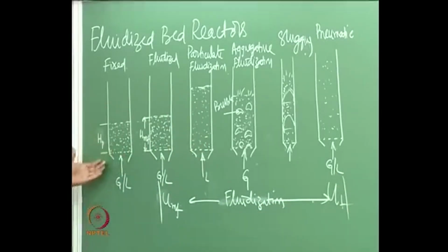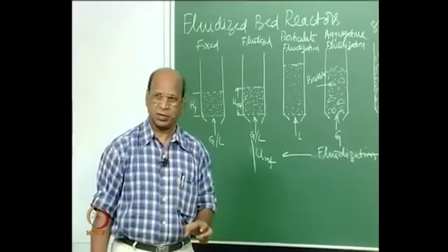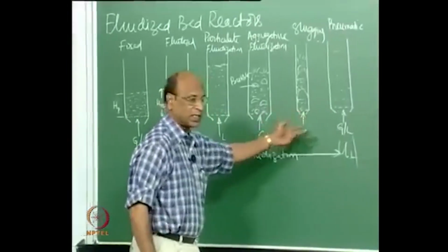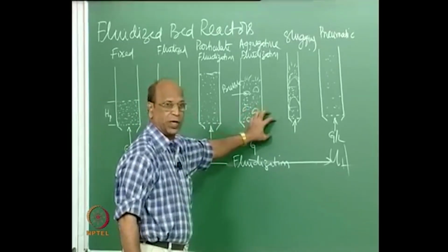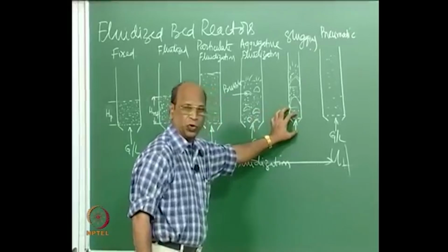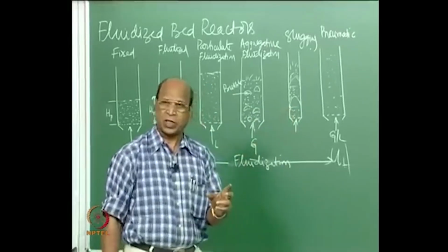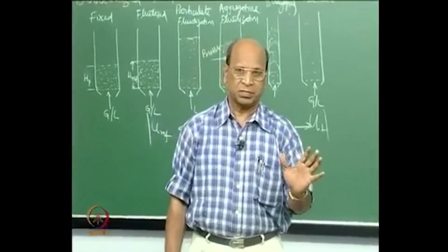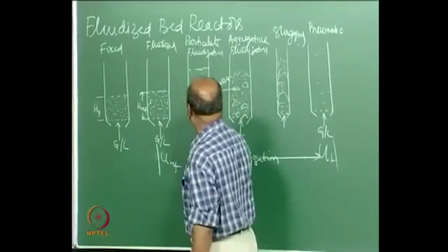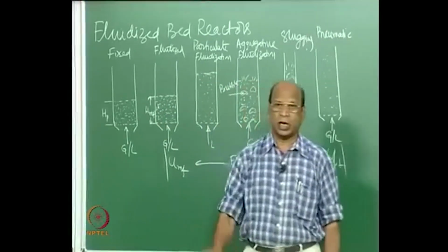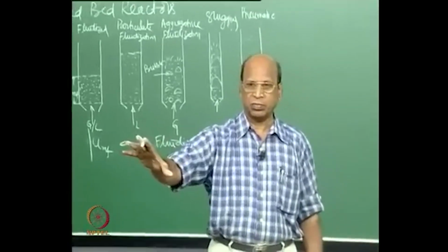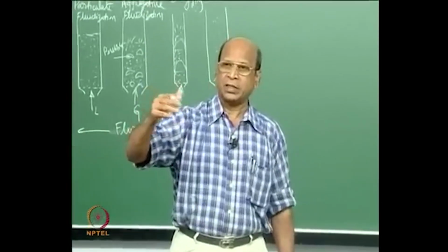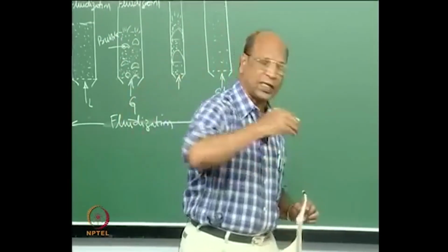Beyond this also no one can use that as a fluidized bed, because it is not simply fluidizing. So, that is the range of fluidization, but in between you have so many operations like this is the normal conventional fluidized bed, then you have a slightly turbulent or aggregative fluidized bed, then in between I have not shown you the circulating fluidized bed. All that depends on how much solids you have in the bed, right. Aggregative fluidization and turbulent fluidization and normal fluidization, you will have 60% solids, 50% solids, 40% solids till aggregative, and also turbulent. Beyond turbulent, the particles start coming out.